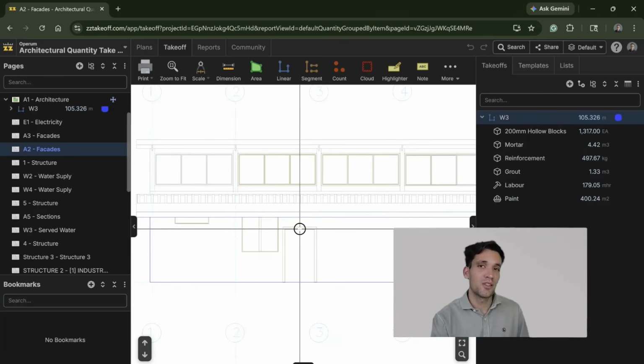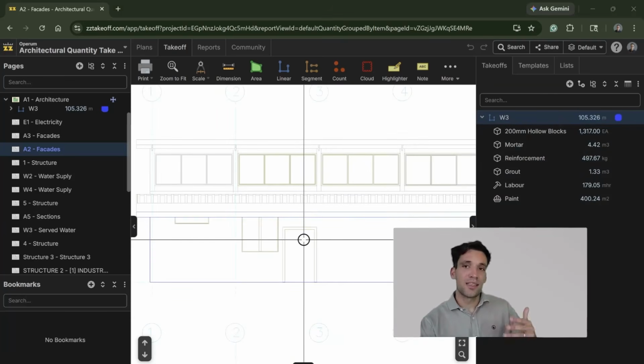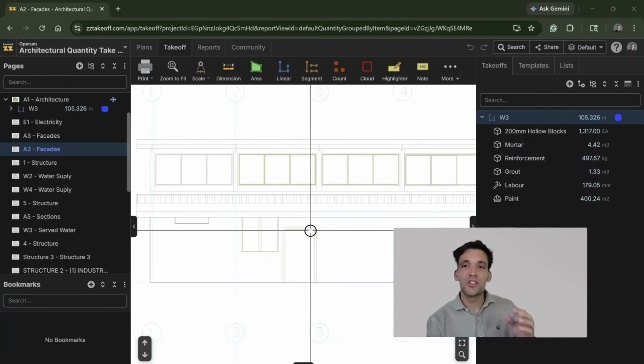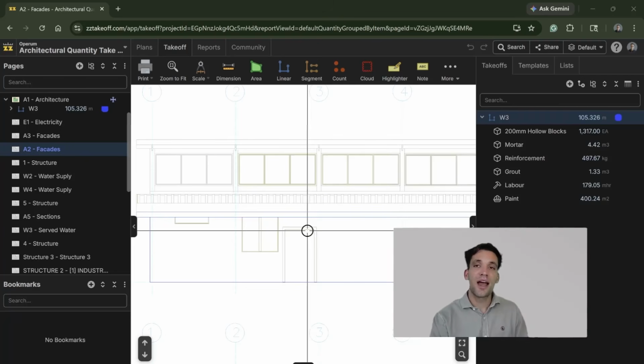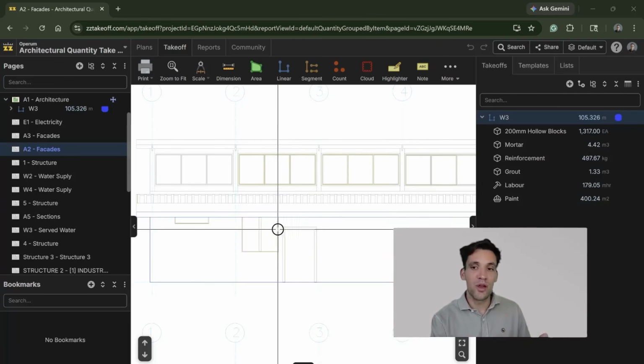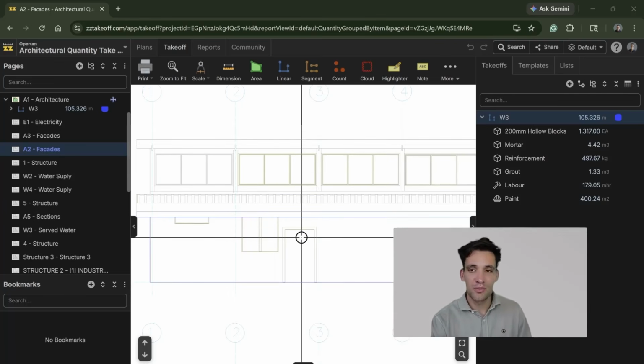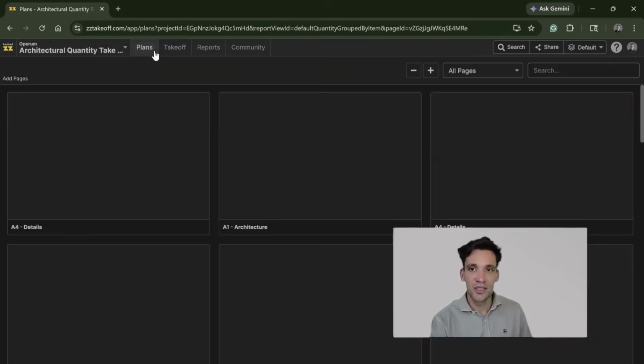So there's a couple of different ways you can deal with this. When you actually go and count the door spacings, you can just put a note in there that you have for that area. For every door you count, you have a negative wall type 3 or something. Or for every window you count, you can have a negative wall type associated with that. And that is just a placeholder for when you go to actually export your takeoff to Excel.